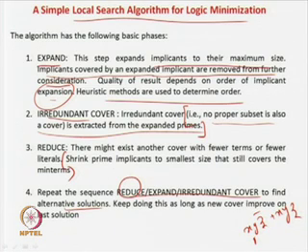So shrink it. Do not think about any prime implicants in this case, because you shrink the prime implicants to the smallest size that covers the min terms. So in this case that is the resultant. If you keep on reducing, finally you will have prime implicants in the end that will actually cover all the min terms. But Espresso does not think about it, it first reduces.